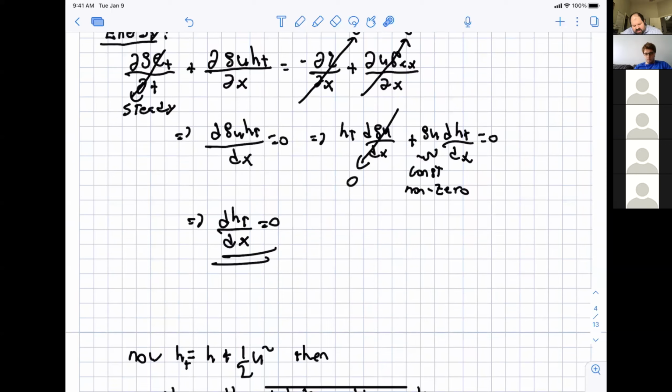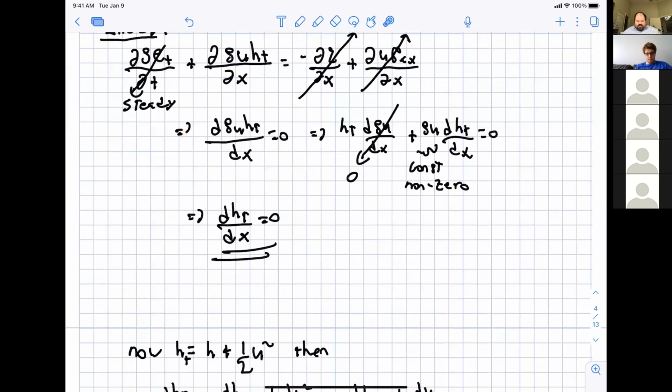And again, in this expression here, does the enthalpy include the enthalpy of formation or not? It does. Yes, because it's not equal to anything. That's right. One thing is, you need to get used to recognizing that very fast, because a lot of folks will just list the governing equations, and it'll be incumbent on you to determine whether they include the enthalpy of formation or not. So you'll have to look at things like this to tell. That's part of why, if you work with combustion like this, you'll get good at recognizing the various equations, because there are so many different forms of them. And they're not always explicit about which ones they are using, so you need to infer yourself.